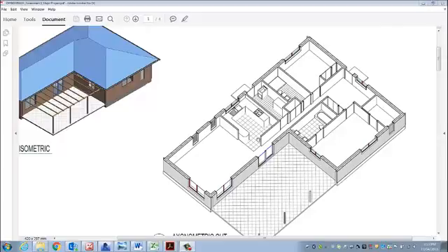You can see that it's a very simplistic view of a kitchen, and for those of us who have looked in any detail at the kitchen, you would know that it's got a bench top and then cupboards or drawers underneath, and then it has a skirting or a kickboard that sits underneath, somewhere between 100mm and 150mm high. Now what we've done here, just to keep things simple, is that we're going to just block this in from 0, which is our floor level, up to 900 high, the standard height for a bench.